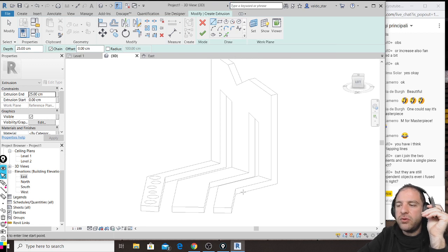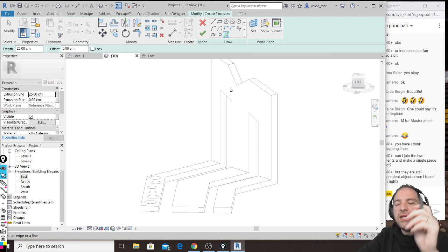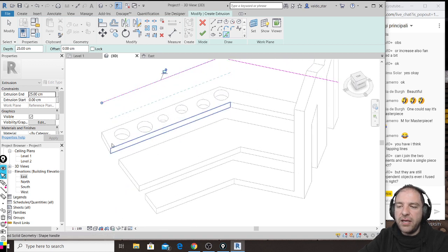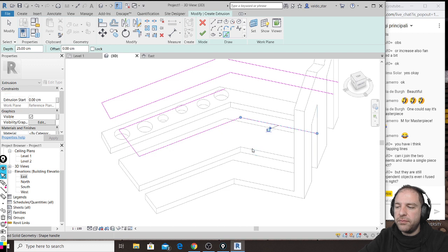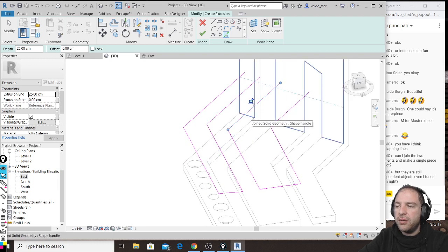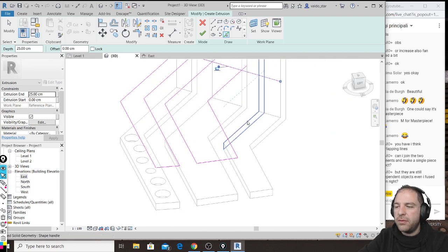So I was saying I want to pick lines instead of redrawing. Can you see this button here, Pick Lines, that we have used to make floors? My plane is up here. I click Pick Lines, and if I pick edges of my lower shelf, they are projected directly on my working plane. Okay? Pick, pick, pick, pick.